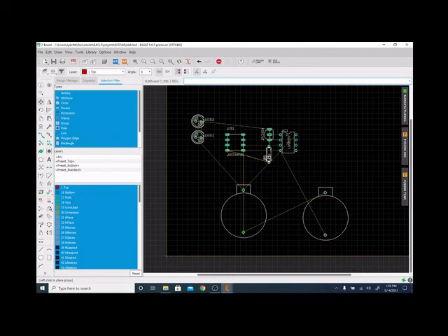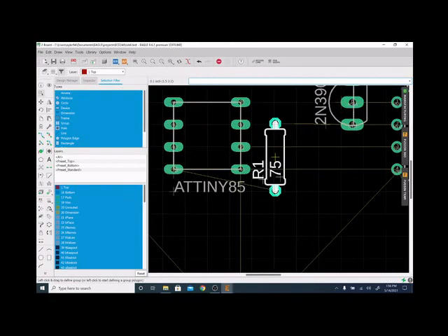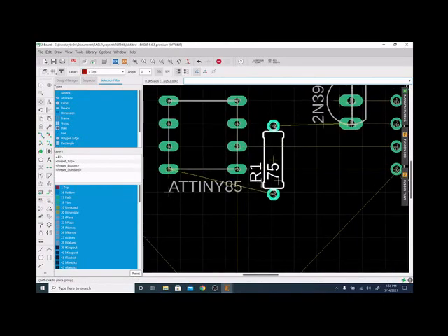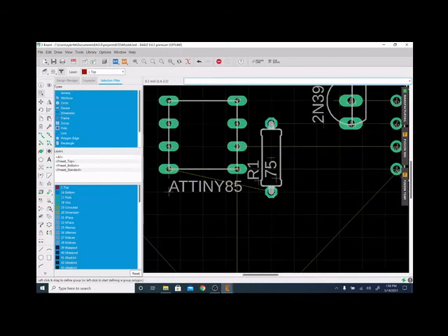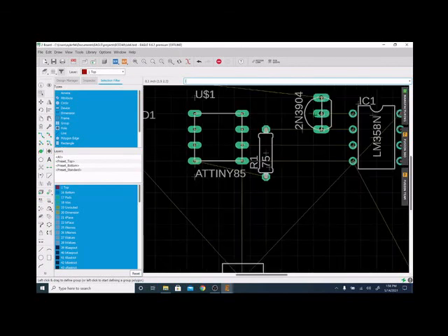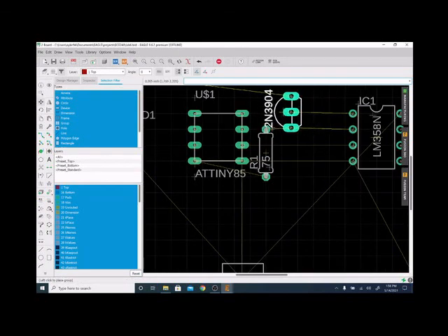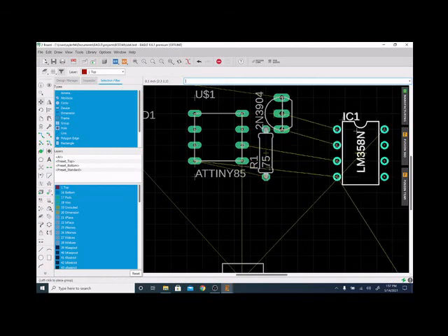Okay. This is, for me at least, kind of the fun part of circuit design, because it involves a lot of puzzle work. You're just going in there and seeing what fits well and where exactly you want to place things. Now, if you notice, I'm using my alternate grid to move my components. So instead of the anchor being on the grid, I want my points to be on the grid. And that'll make sense in just a second. Because when I put this here, or I guess I'll explain it in a little bit.